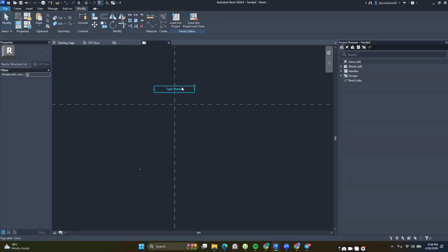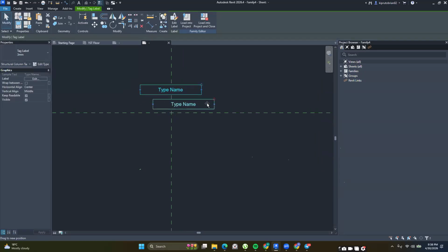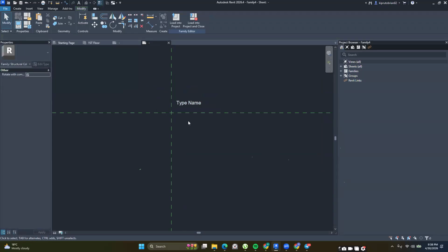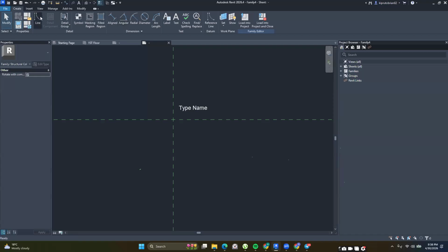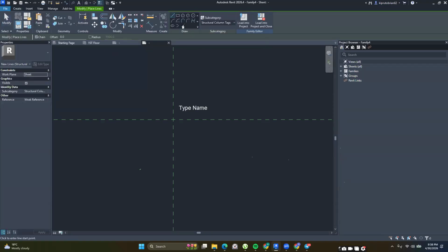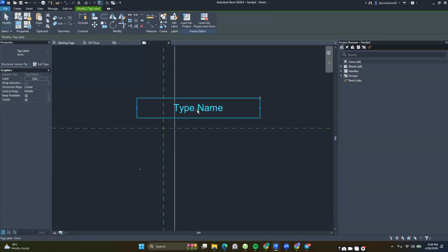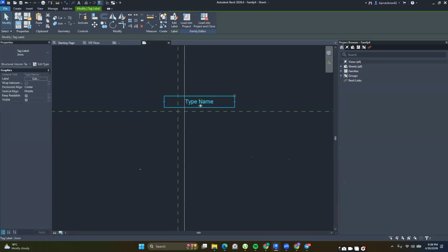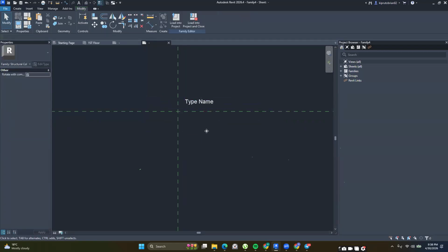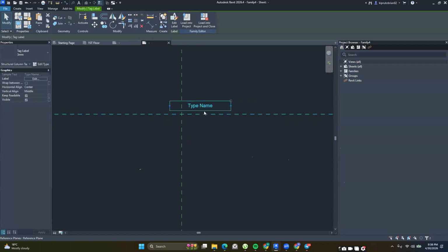All right. And now that you understand this, I'll just place it slightly to the right. Okay. So for this one, I'll do something different. I'll just come to create, and then I'll draw a line, say pick lines here, and then I'll offset it slightly, say by 5 mm to the right, and place it somewhere there. Okay. Let me have it there. Okay. So you could just have it there and then delete this particular line. All right. Then select this particular